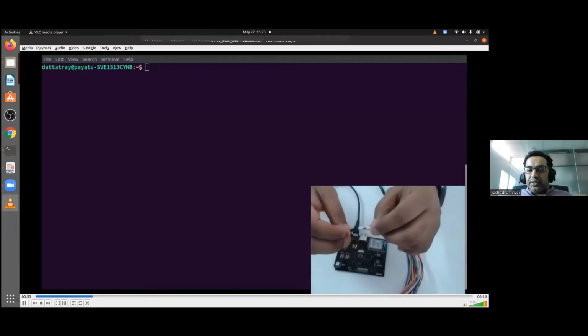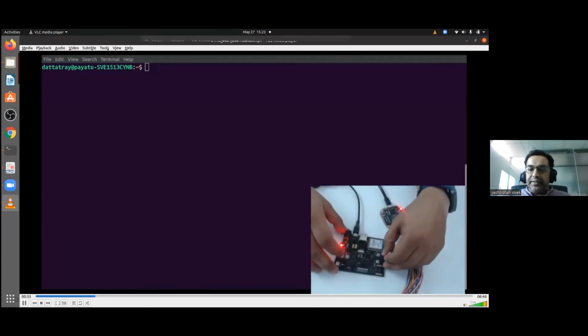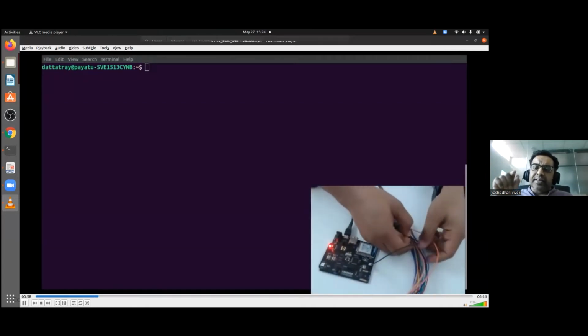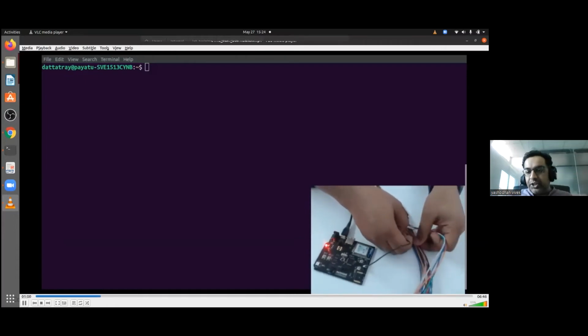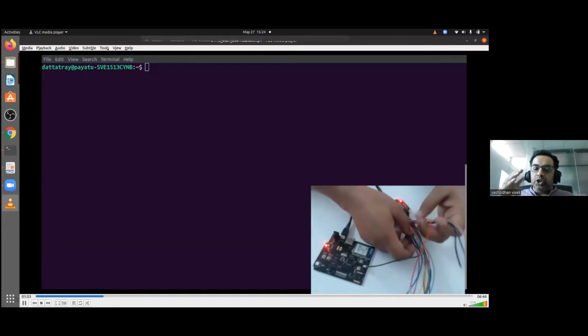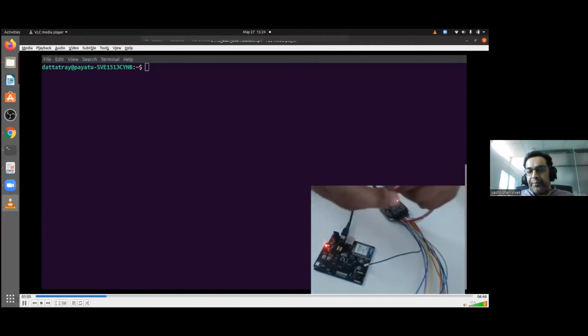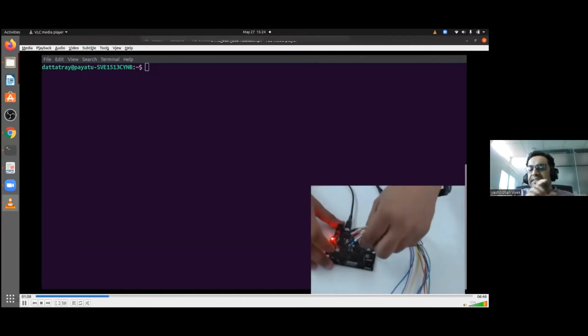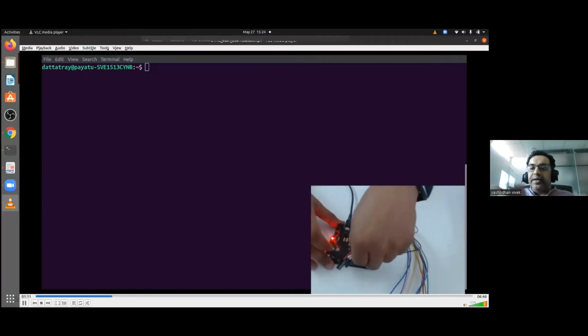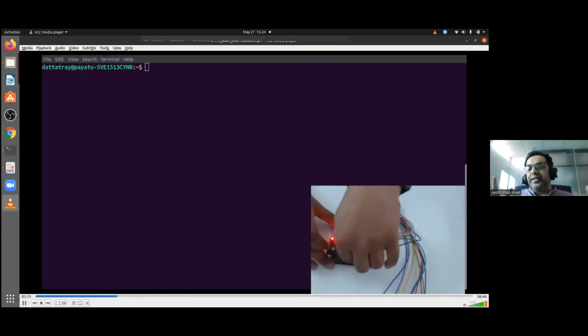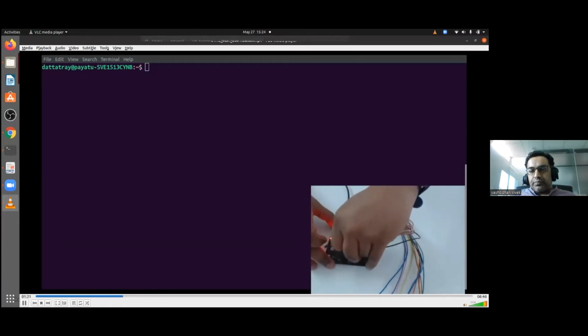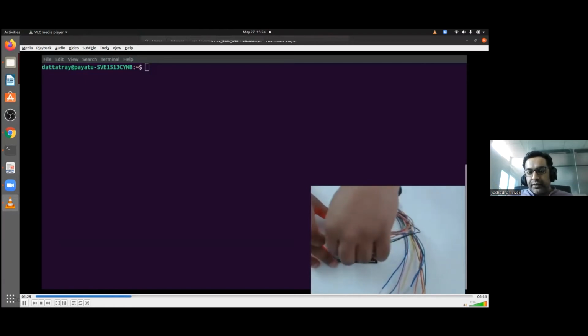The first part is connecting the ground pin, because that is a common thing that we need. Since this EXPLIoT bus auditor has 16 channels, the rest of the channels need to be connected to the particular pins. Since the header has 8 pins, we connect all those 8 pins on that header, just to identify which pin is actually doing what. With those female to female connectors, you can simply connect that.